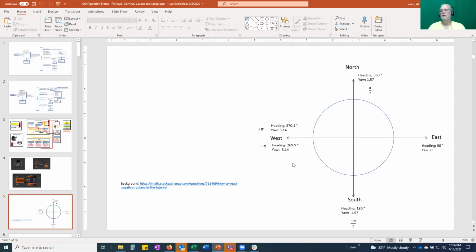My question is, where should that happen, and what would be the easiest way to do it? I don't recall looking at the GPS ODOM Pi specifically saying we are taking care of that problem. So I don't know what's coming out of there, if it's still in GPS or if it's in ROS conventions at that point. But if you look at the NavSat transform node that comes with the robot localization stuff, there might be a parameter that says convert, or it may just automatically convert it for you. Again, I'm just trying to figure out where that should happen.